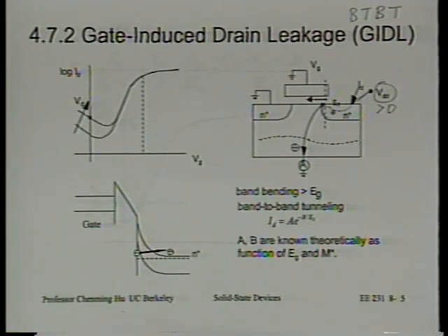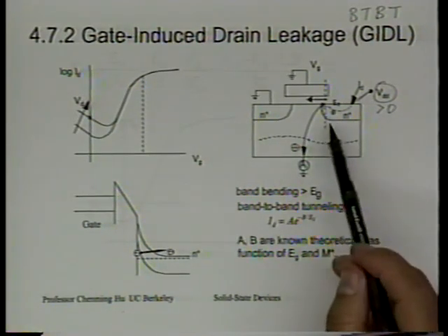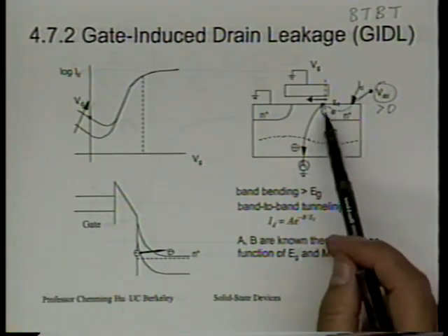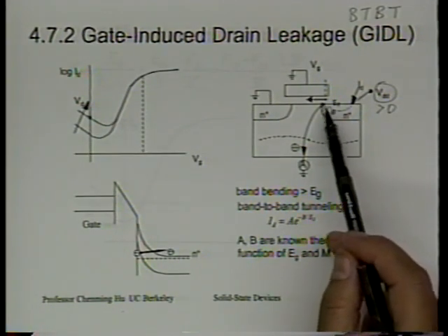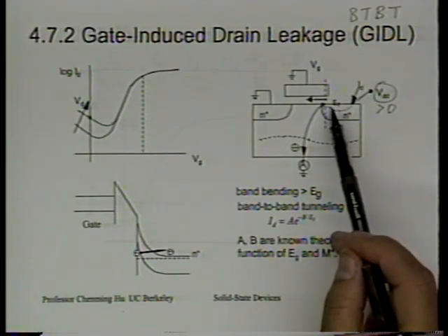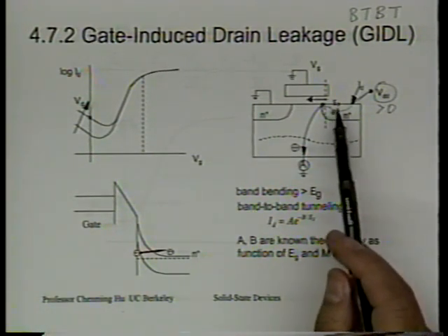All right? Okay. Another way to understand that really is this: we will never be able to establish an inversion layer because anytime you have holes here created maybe by thermal generation, what will happen to those holes? Holes will simply flow out.